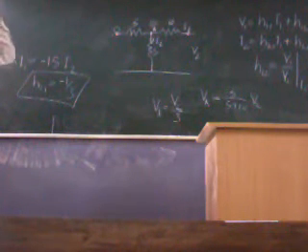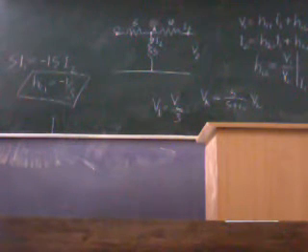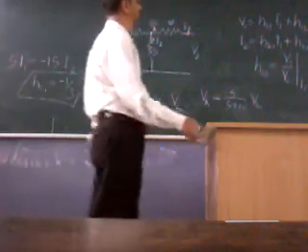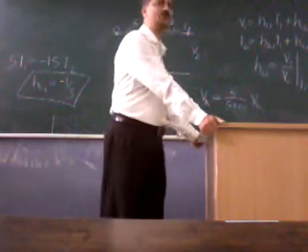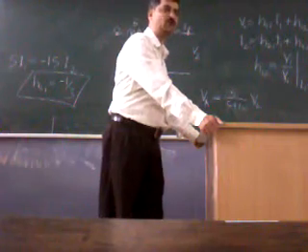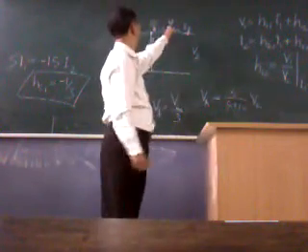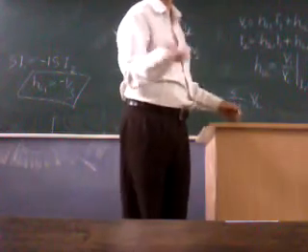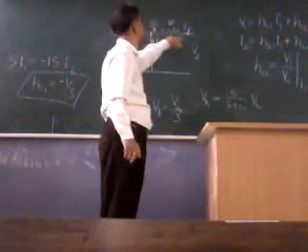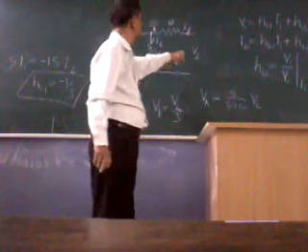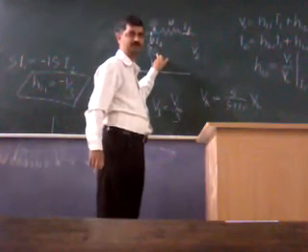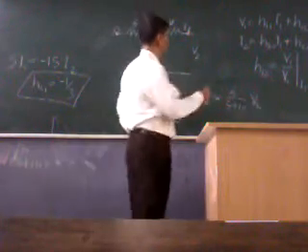Now H22. H22 is very simple. What is H22? It is the ratio of I2 upon V2. What is that? 1/15. H22 is 1/15 because, since this current is not there, the total current is I2. So V2 is equal to 10 plus 5, which is 15 I2.